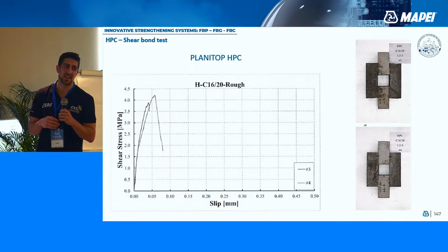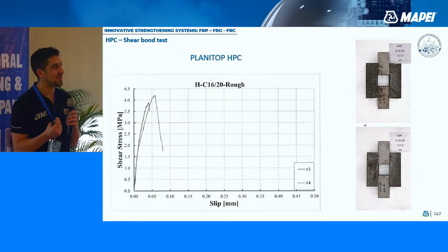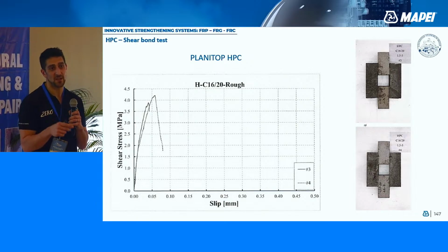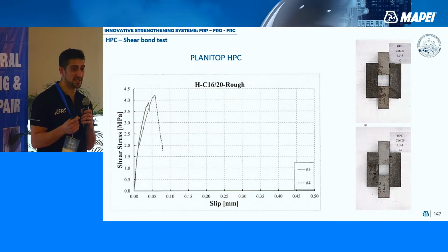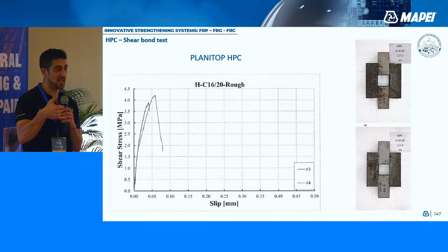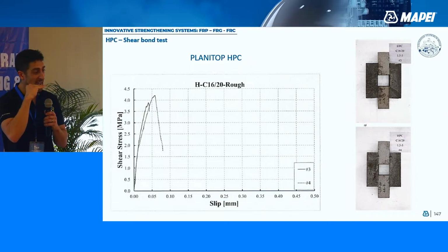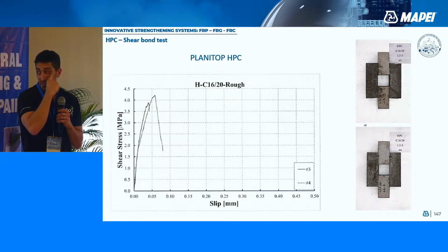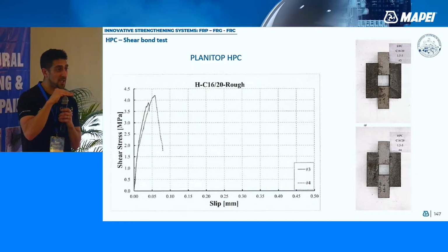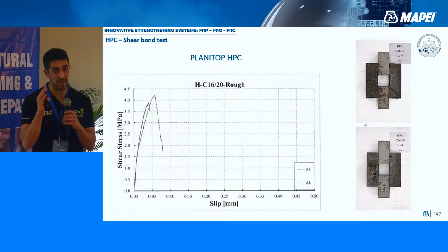Starting from the geometrical properties of the section, so the moment of inertia, the acting shear, the elastic modulus, and also the effective depth, we are able to calculate the acting shear stress at the interface. And most of the time it never exceeded 1.5 megapascal.